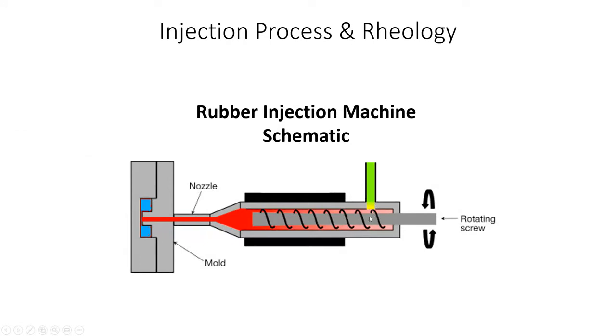And through the screw and barrel, there's a mastication process. This screw and barrel can turn faster and actually move materials back and forth and mix them. And some screw and barrel systems even have what they call a flight schedule. The movements change volume and push materials back and forth, creating shear heating and shearing in this system. And so we measure that.